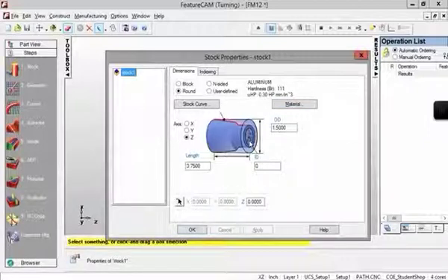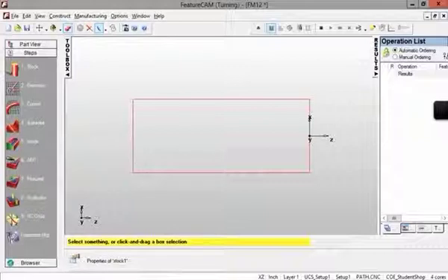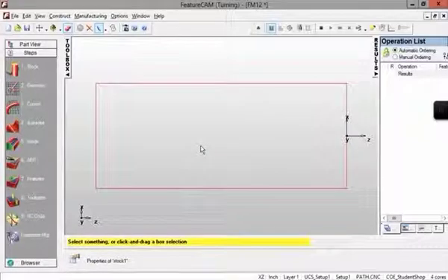Okay, I want to point out that the z-axis is actually the rotational symmetric axis, right? And usually by convention we set it at the point right at the top of this cylinder. Okay, press OK. And it shows you this red box. The red box actually defines a cross section of the cylinder, and actually you can still observe those blue dots, but since I already told you we are lathing this, it is because it's rotating the workpiece, and we just keep the upper part clear. That's already enough for the machine.